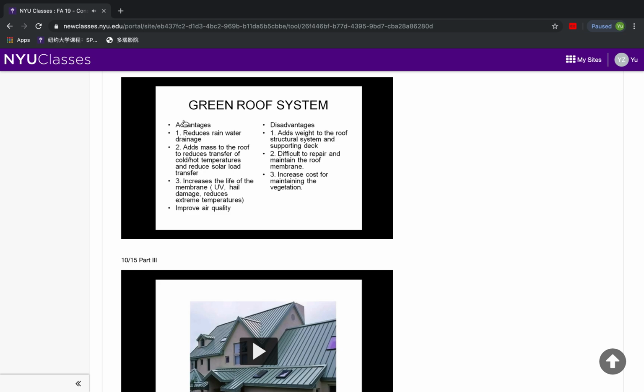So not only is there the water that gets used to feed the plants on the roof, but sometimes green roofs also route this water to other purposes in the building outside of drinking water, such as toilet water, wastewater, and again for watering plants instead of using treated water that comes from the water supply system. The green roof itself helps heat or cool the interior of the building, reduces the solar load, and actually acts as an insulator. You also get the added benefits of having trees, plants or grass that can help clean up the air and the environment around you.